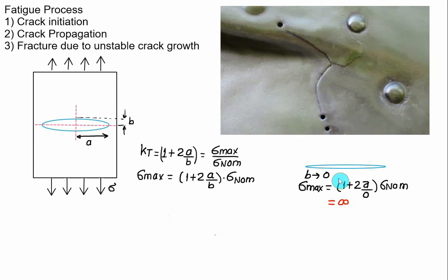Stress concentration is one reason; the second is temperature also. Not only brittle materials fracture, most materials have a ductile to brittle transition temperature, and when the temperature drops, the crack initiates, and the crack propagates only under tensile loading. As the tensile loading shoots up, the crack propagates. Crack propagation means the crack will enlarge.